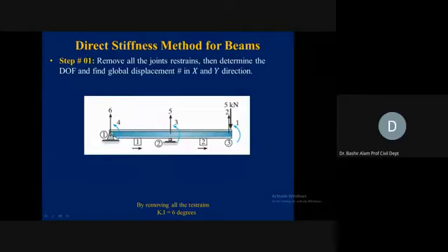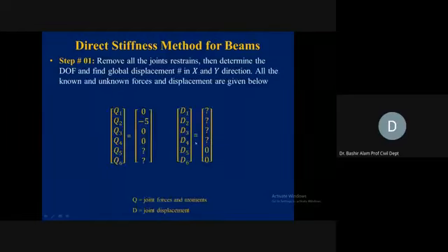Those become our unknowns. And the restraints were this vertical displacement, which is 0, and this D6 vertical displacement at joint 1, again 0. So these are known ones. Straight away for D5 and D6, we can put 0, 0. And those free joint displacements, we put with question marks.